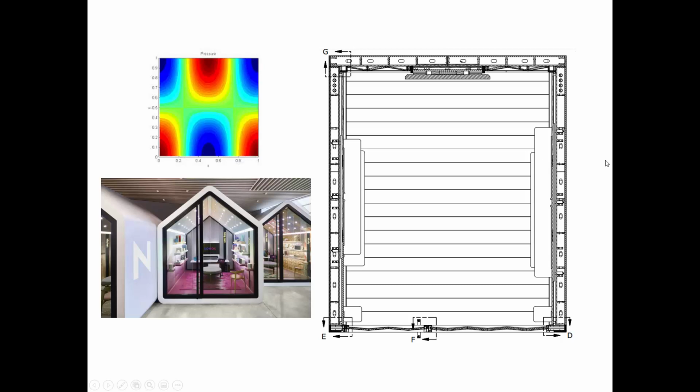But anyways, to some of the other things we've talked about in here. I'm going to get more into the sound isolation and showing some of these details here in a minute. But first, this back wall, that's the glass. So we have this sawtooth. We couldn't really make this absorptive, not effectively absorptive, and didn't want reflections off the back wall.